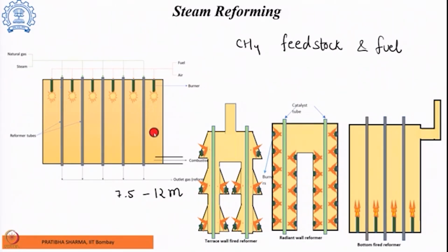The combustion gases carry the remaining heat, and these gases are hot and have high grade heat that can be utilized in heat exchangers for either preheating the natural gas or for steam production. So there could be a heat exchanger which extracts the heat that comes out with the combustion gases to either preheat the mixture or to generate steam.